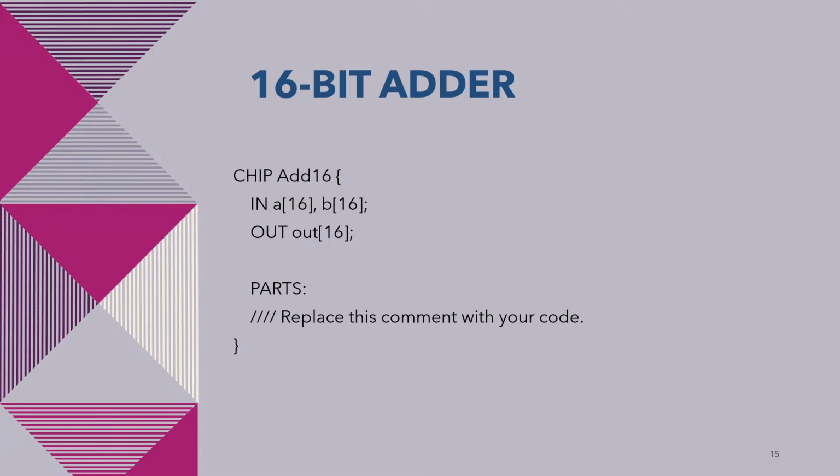And just put them in a series, 16 bits. The first one will be the 0 bit of the operation. Then you'll have the 1 bit, the 2 bit, the 3 bit, and put the wires up so that the carry from one column goes over into the next column, and so on for the 16 bits of your operation.